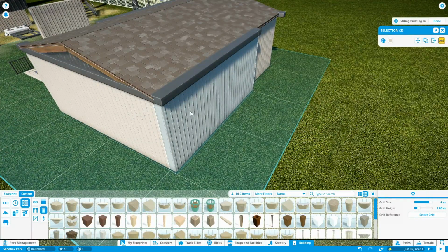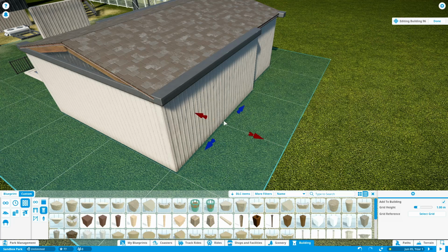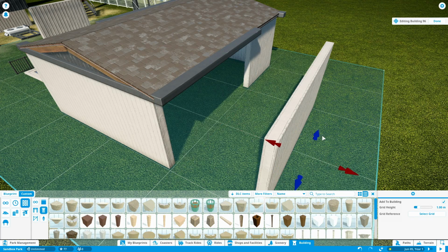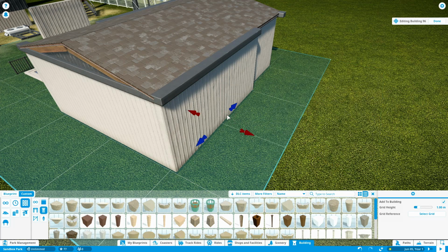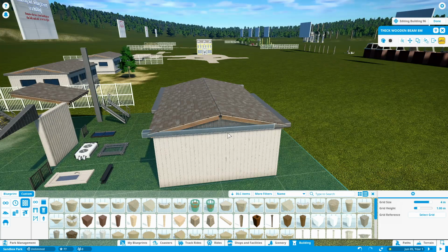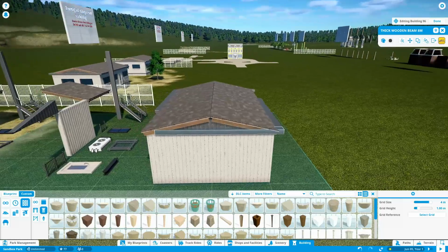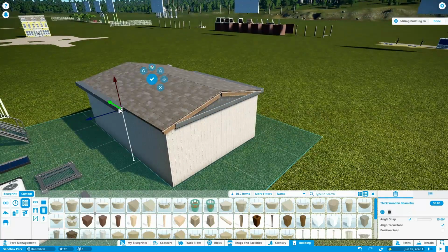So the other way you can fix that is by selecting all of them, hold down Control, and then M. And so Control M allows you to move pieces together without changing their elevation. And actually it might not work for two. So Control M on one piece. Yeah. So it allows you to just sync it into the correct level. So I'm actually glad that happened, because you can see what kind of issues can typically come up here. Yeah, so we've got those, and then we'll just complete these together.